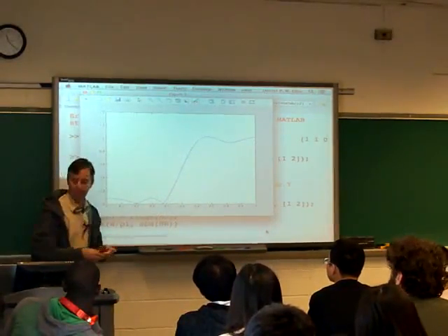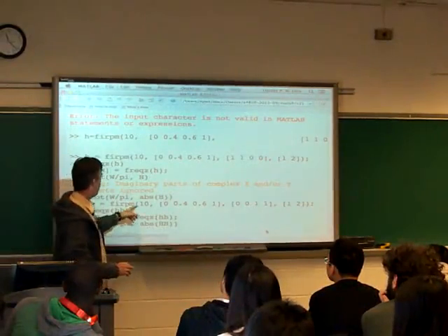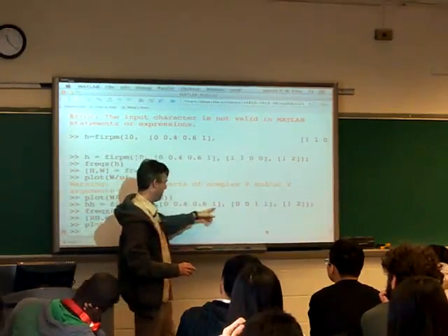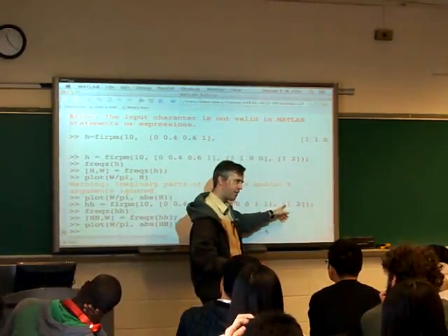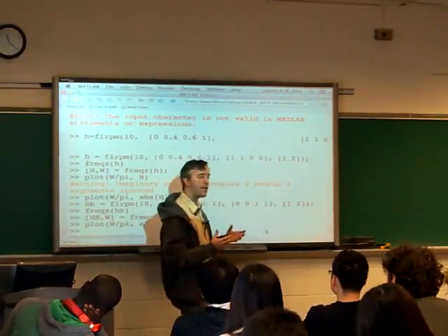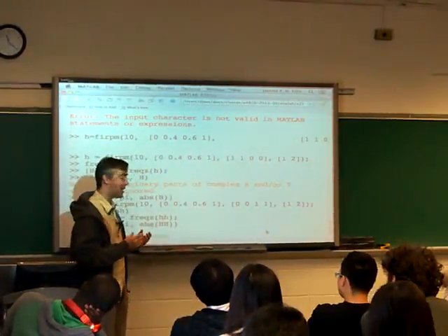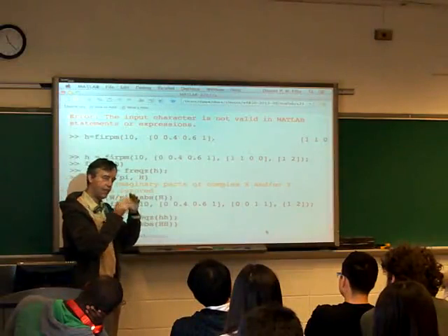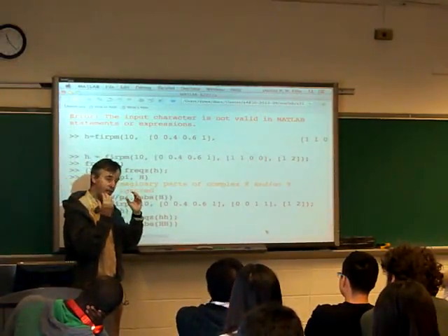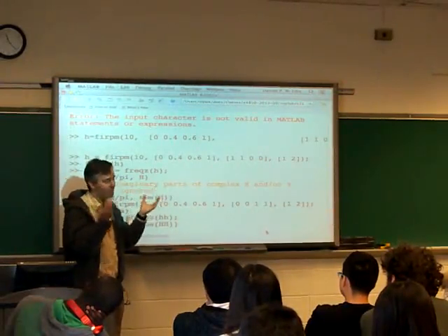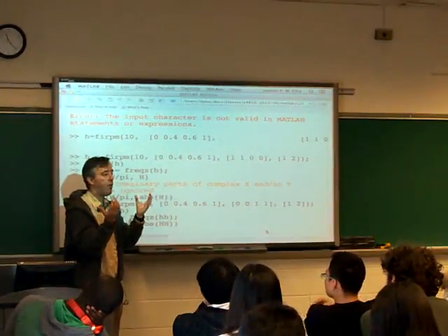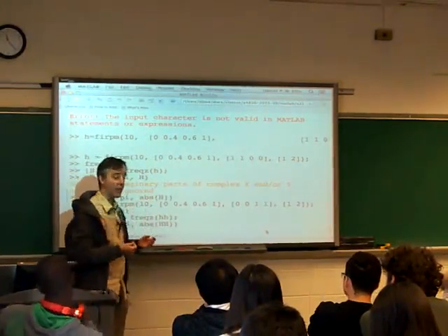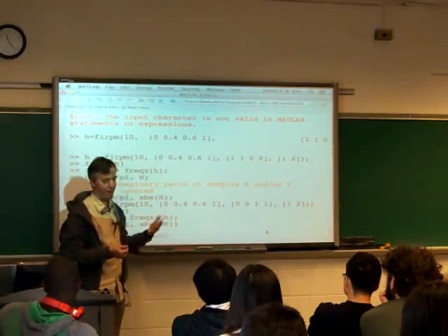So we've specified the order of the filter, exactly where the bands are going to be, the gains that we're going to have, and the weights of the errors, which is the relative size of the errors. But what we haven't specified is the actual size of the errors. It's going to find the filter that meets these criteria, that has these particular band edges and has the smallest error that just touches those error limits. The one unspecified thing is how big those errors are. So it finds the smallest error, but you don't know how small that error is going to be until you actually build it and try it out.